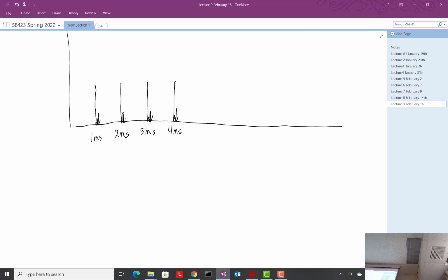So where does the interrupt occur? Your interrupt function is happening right here, in time. So you can use that interrupt function as your every millisecond interrupt and consider that you're sampling at a millisecond. You don't have to take into account that little delay from when you told it to convert to when the conversion is done.